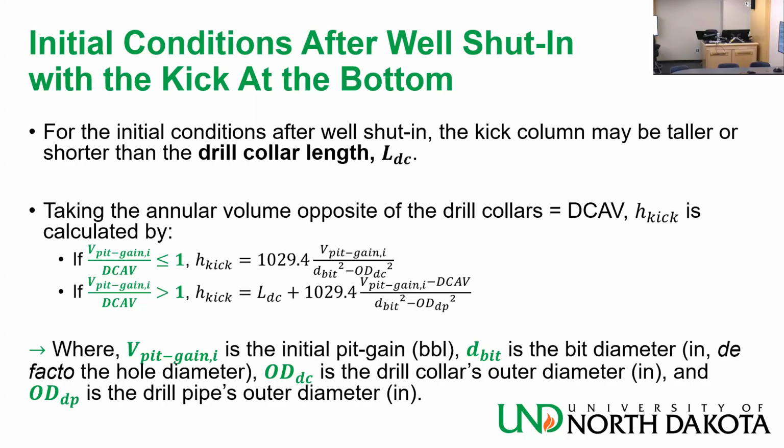And even if you have data from nearby wells, it doesn't mean that the data that you have is representative. So it's not possible in the field to know the height of the kick without calculating it. You think you know, you make some estimations, you have a range.